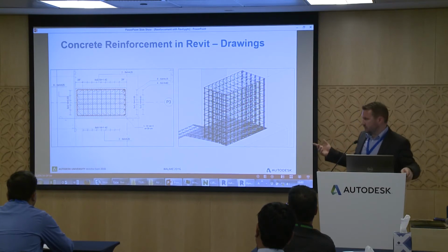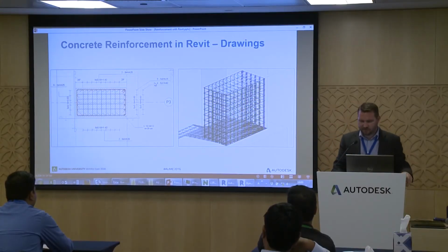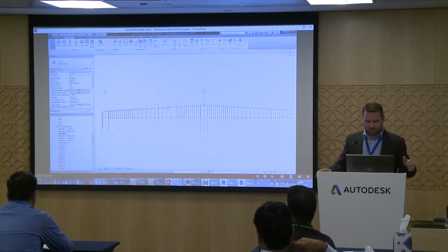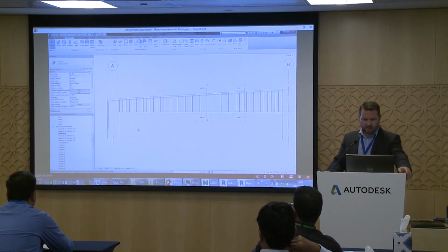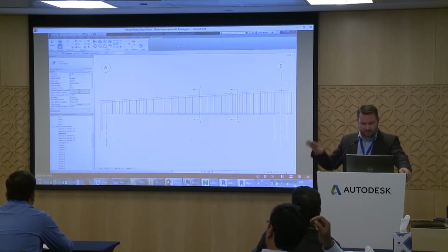After, you can do filters, of course. You can do filters in 2D and 3D, on diameter, on parameter, whichever new parameter you have, but you are in Revit with classic family and classic element. It's not something weird. Okay. If you don't know how to tag here, you will go to Annotate at the last part, and here you will select.